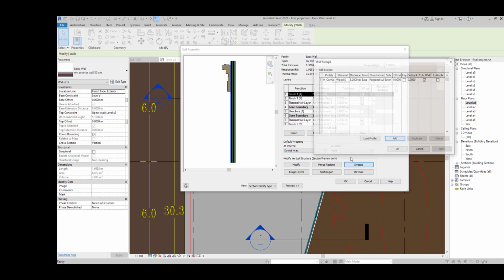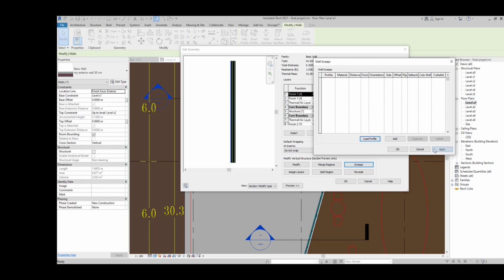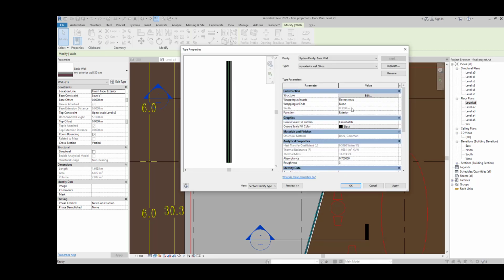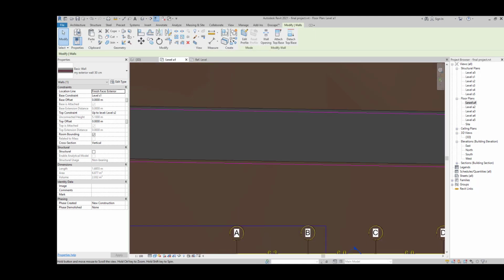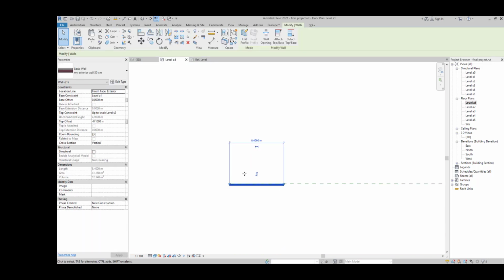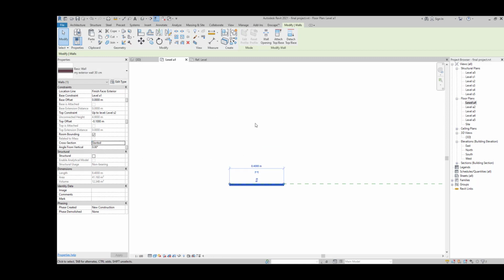We are just able to design our wall with one material in model in place, but in wall right now we have the option to use, for example, a different angle, a specific angle for our wall, and everything is going to work perfectly. And this setting, you can find it very easily here by just pressing on your wall. After that, you are going to have the option here, which is cross section. You can change your cross section from vertical to slanted. Your wall will be slanted.